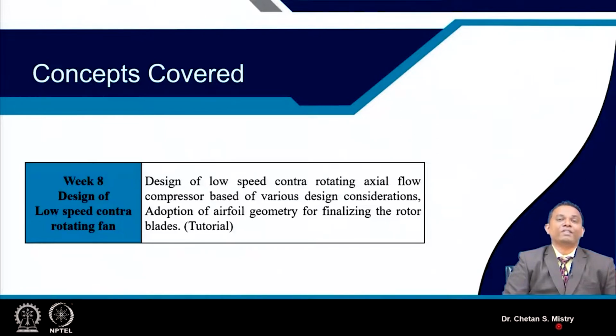What we realized is that when we opt for the free vortex concept, our blades are highly twisted, both for rotor 1 as well as for rotor 2. At the same time, with the fundamental design approach, where we have great control over the parameters, we can make our blade less twisted, and that gives a wider operating range. That is what is expected. Secondly, manufacturing is easier when we go with the fundamental design approach.